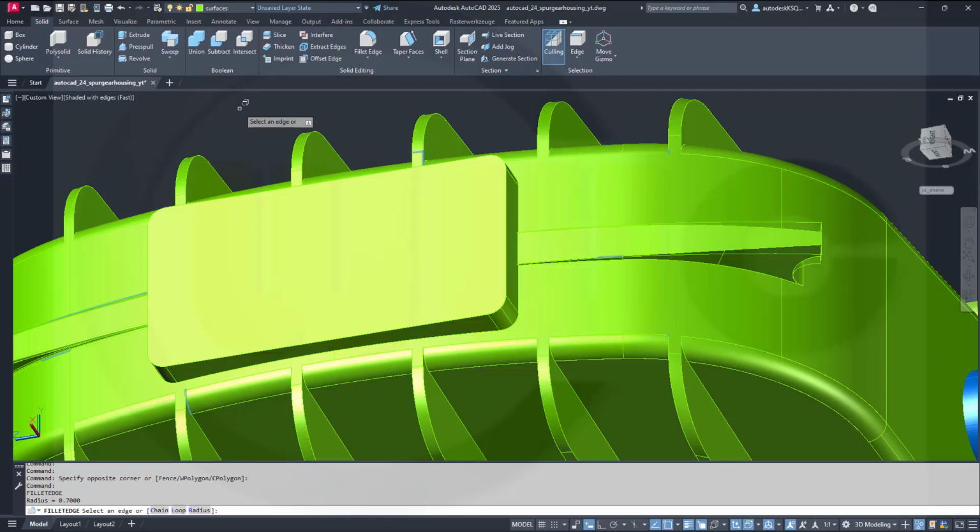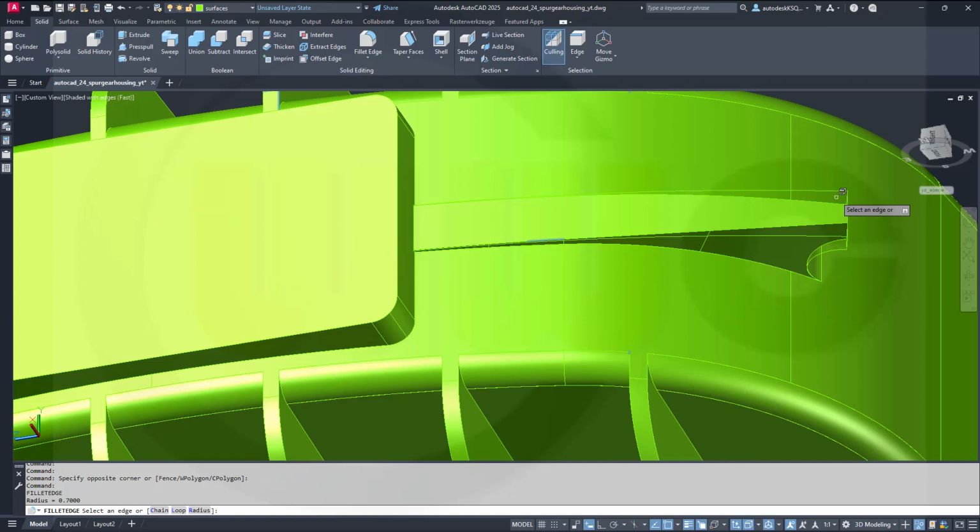Okay, another fillet, same radius, and there is some sort. What's this? These are extracted edges, I suppose. I could delete them. Could I hide them? Because that's maybe a problem if you want to select here the edge. But let's try it anyway.